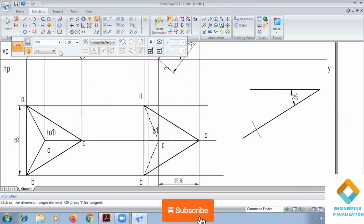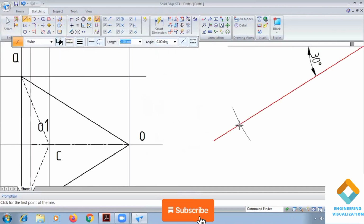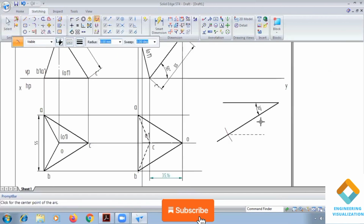So another length we have, that is slant edge 35.16. So these two lengths are required. One length already we have drawn. Now we need to draw a locus line here, horizontal dashed line. Okay, so cut second arc using arc by center. Just move the cursor on the first arc, you will get the reference point. Now type the radius 35.16 and enter and cut the arc.